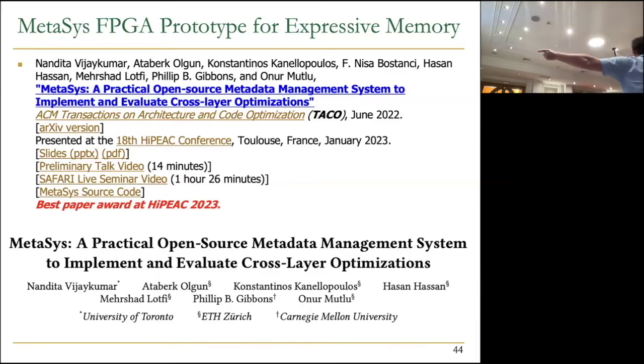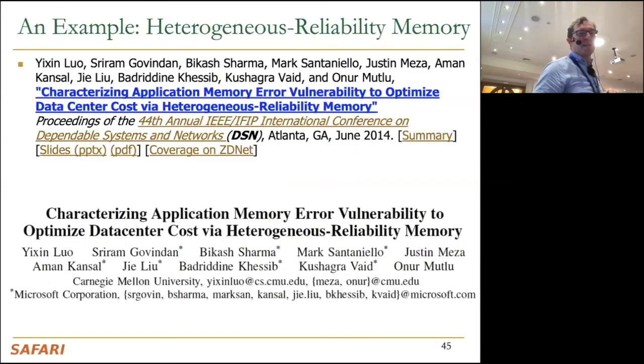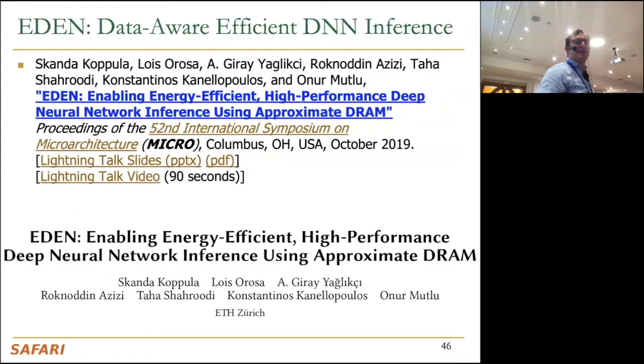to keep track of all of this program semantic information and use it for different purposes. In this case, we have a prefetching example. We also have a security example that does bounds checking. So if the software can communicate, for example, higher level bounds of a program, you can do much better bounds checking at the hardware so that you actually get rid of a lot of the buffer overflows, for example. So there's a lot of applications to this sort of higher level program semantic information being communicated to the lower levels.